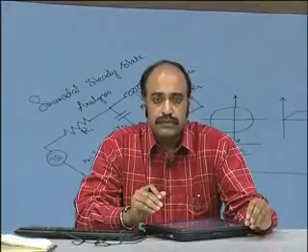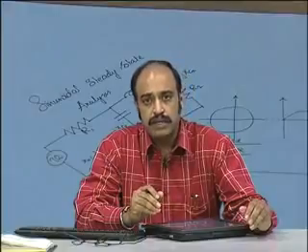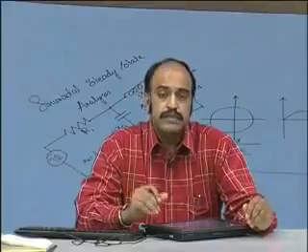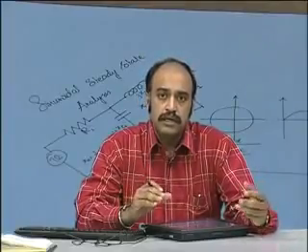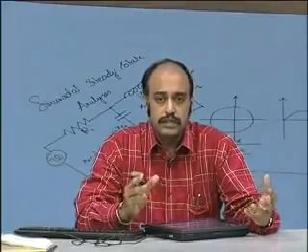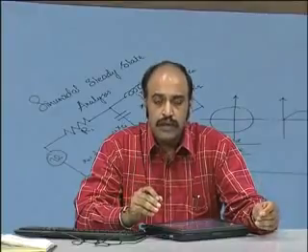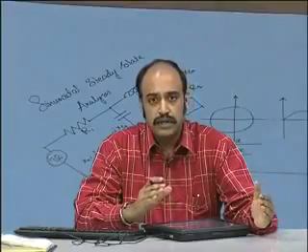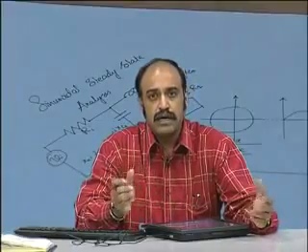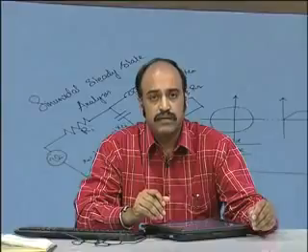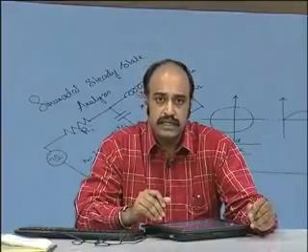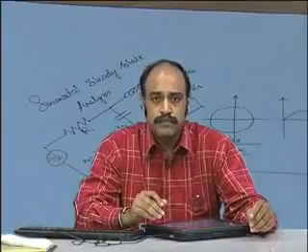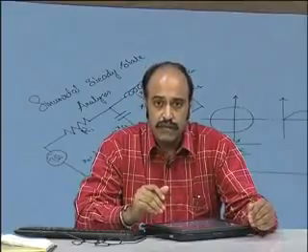Now, in the case of the particular example last class, we saw that for different parameters, for the same circuit, the pole locations can change. And we saw how a fully damped system gradually became a kind of damped oscillatory system, because the pole locations started shifting towards the imaginary axis, and it also became complex poles.